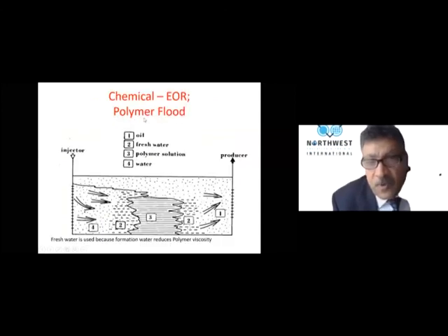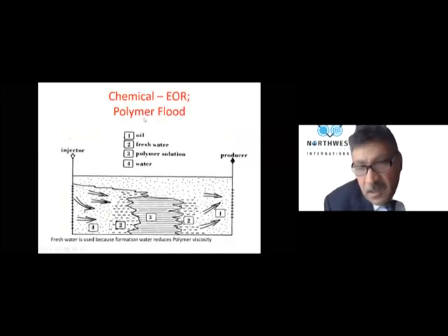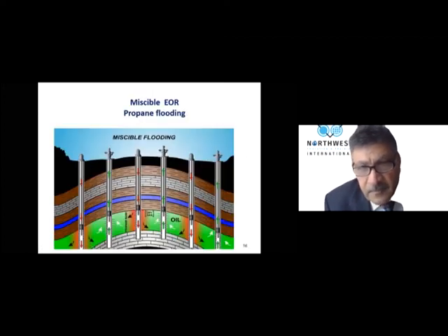And we have also polymer, same idea. We prefer to be a water-based polymer. You inject the polymer inside the rocks to wash up. Here, no pressure build up. Here is merely to decrease adhesivity and build up the sweeping efficiency. Sometimes you can inject propane as well, or butane, or LPG. I don't recommend that unless you have plenty of money, because it's expensive, and also could be dangerous in terms of safety, but they use it in certain countries.